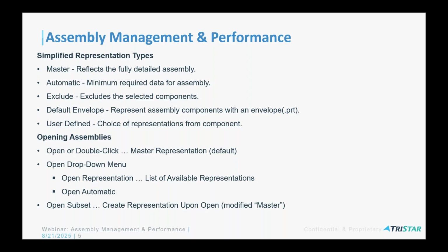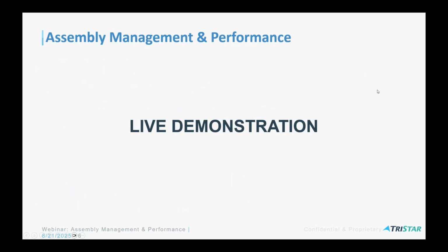There also is a config option that if we create a rule-based simplified representation, to force Creo to evaluate those rules upon opening, and that's also a good one to turn on. And I'll show you these config options in the demonstration. So let's go ahead and get into the demonstration.